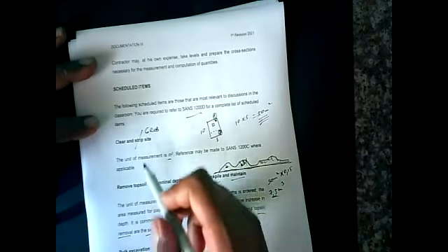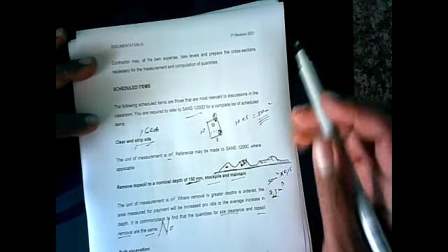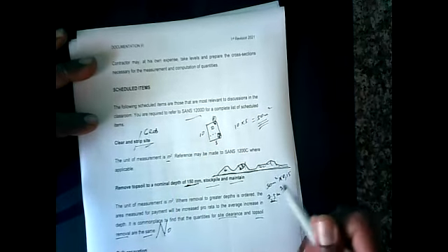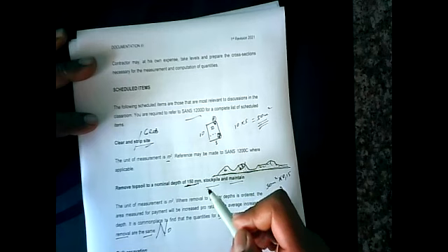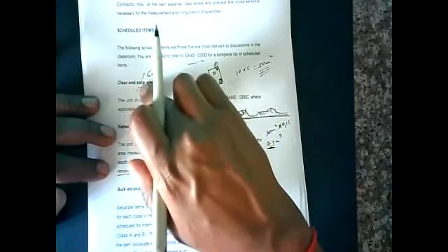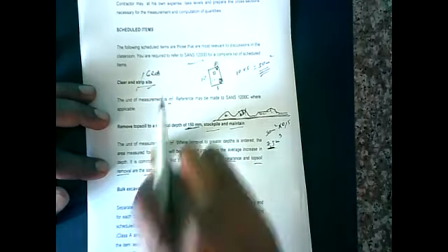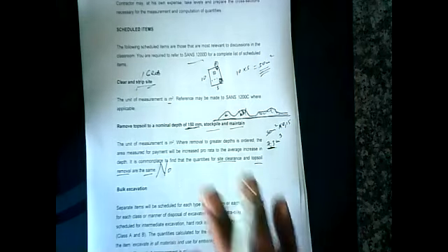But if you have an area, now what do you do with that? Yes, we cut the grass and clear up for that area. We can quantify that. Now you've got an area of topsoil? No, that doesn't fly with me. Reduce it to a volume, and we can work with that in terms of a costing to remove. All right, so for now, clear and grub is an area, remove topsoil is a volume. We'll see that in a calculation as we progress.